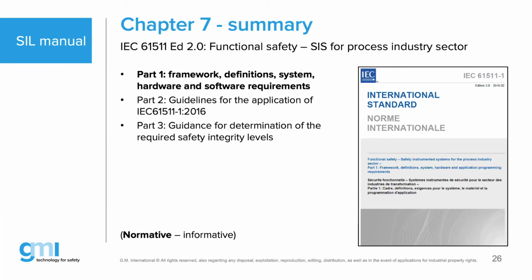So a SIL 1 is from a different person, a SIL 2 is from a different department, can be in the same company, and you can make a self-declaration that you comply to SIL 1 and SIL 2. But for a SIL 3, as per 61508, you need an independent party. It shall be assessed, and that is where the independent bodies are coming in. But of course, that does not mean you get a certificate. You might get an assessment. Exactly. So that's maybe the back door for a SIL 3.